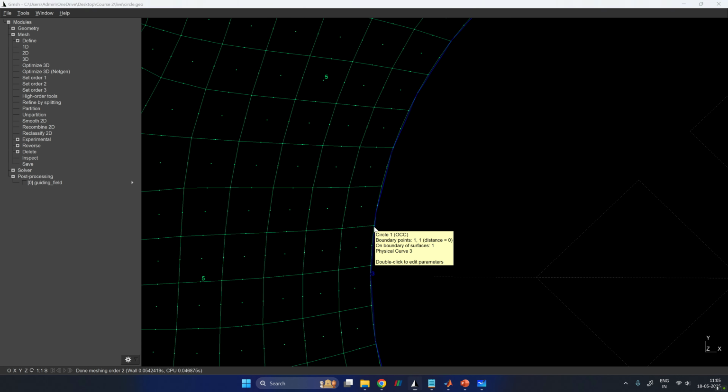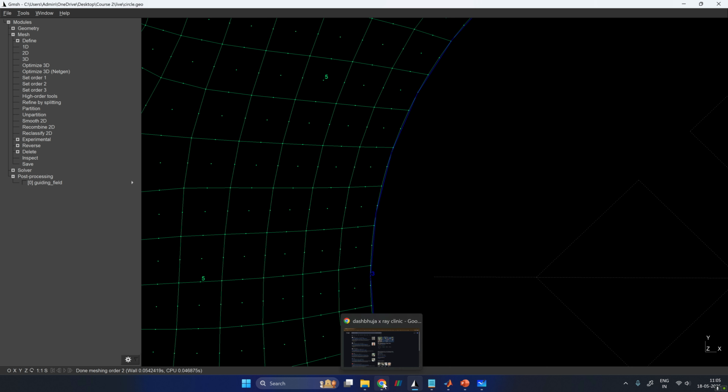I have to calculate the integral based on the 1D Lagrange polynomial. So if I have used Q2 here, I just use quadratic 1D shapes. I do the integral, and I can just add them to these nodes. So this is how I can assemble my stiffness matrix. We have seen this for the 1D case. In the 1D case, it was just a point integral.